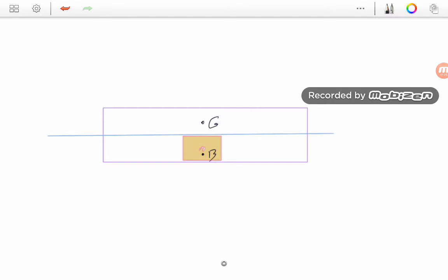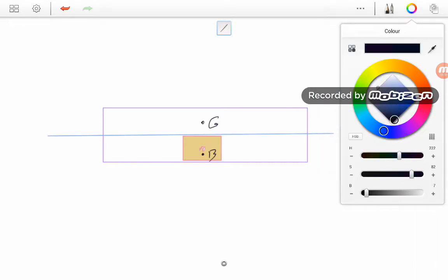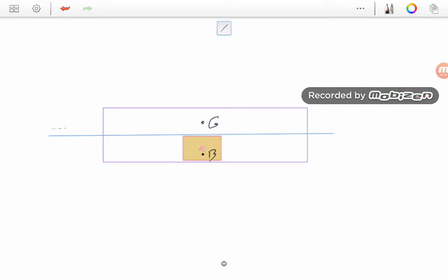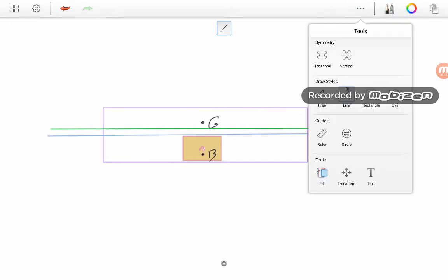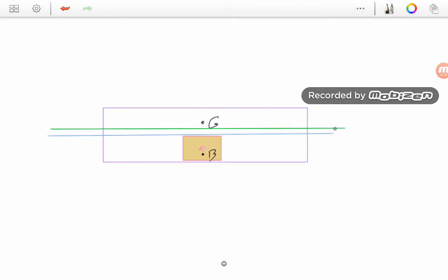After we lose this compartment, the water plane area will be changed. Why? Because the vessel will sink, and the new water line will be here. Okay, this will be our new water line.